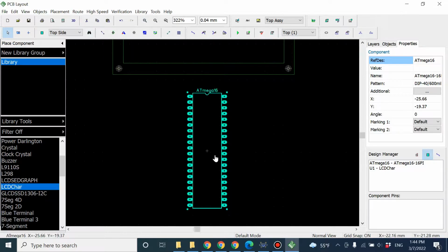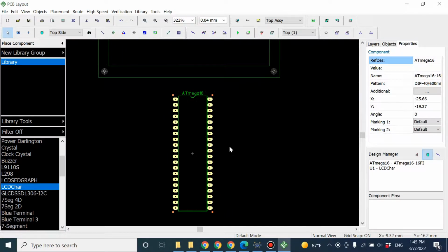Okay, it's thicker. It's better when you want to solder your component to your PCB. They have a better strength, so they won't come off by heat, or you don't destroy your PCB. So always remember about your trace and your pins.